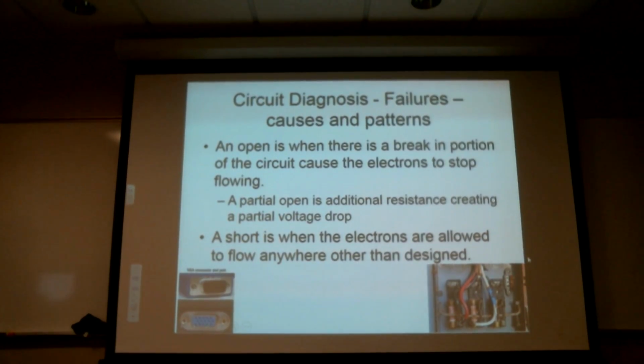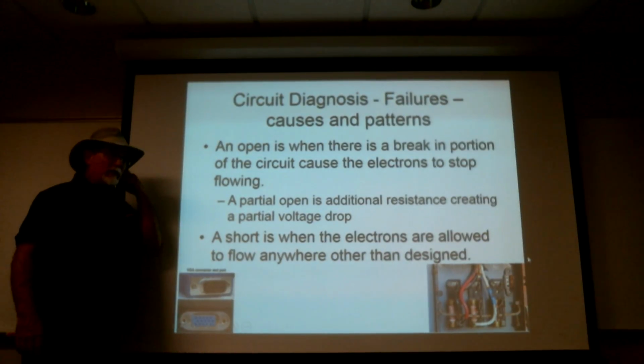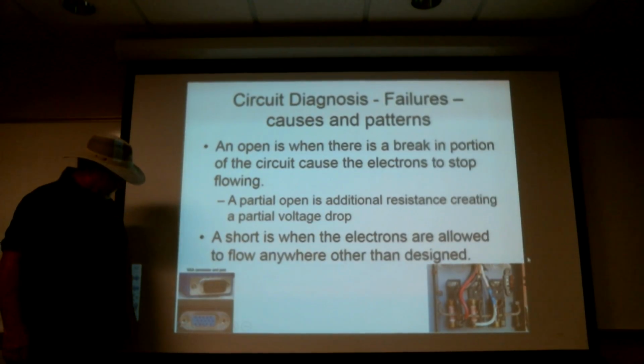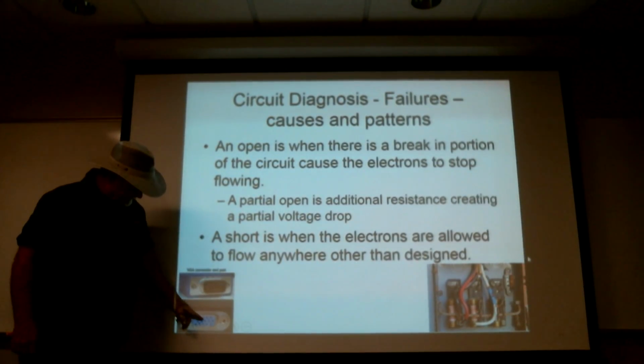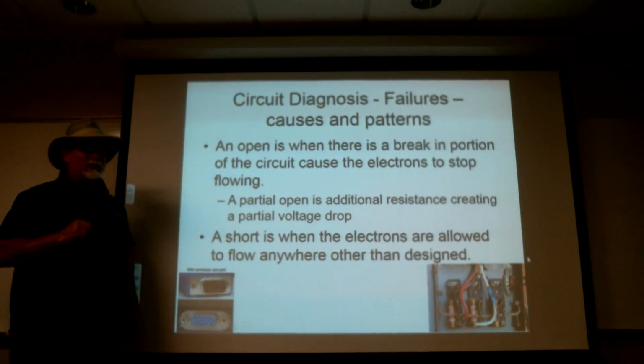the most common place you're going to find opens, unless something really weird happens, is going to be at connectors. You're going to have a pin pushed, a pin broken or pushed back. Might be something happening there. This is kind of hard to see if there's a problem unless you get a bright light and look in there.